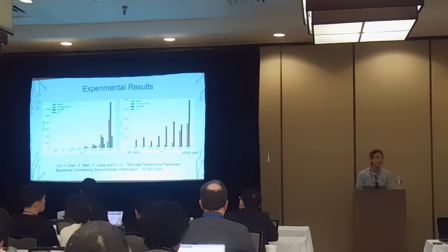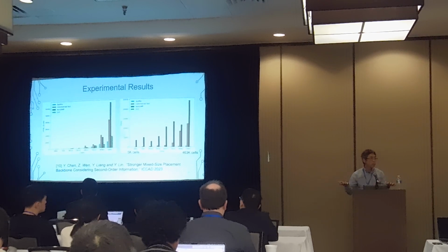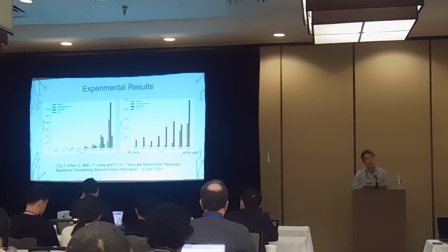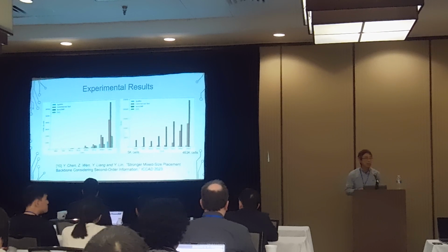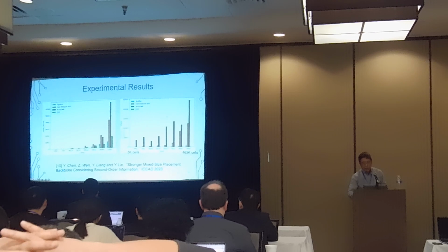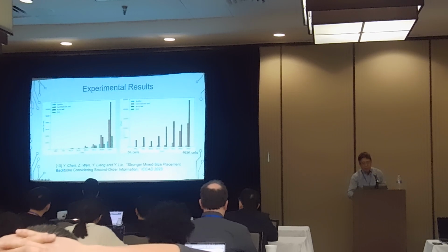So one reason is that the other works are general purpose mixed-size placers, and ours is customized. It's not exactly a fair comparison, but just to show you, there's actually room for this. If you customize the physical design, you can get good improvement. And also, if we look at the runtime, our runtime is so much shorter.